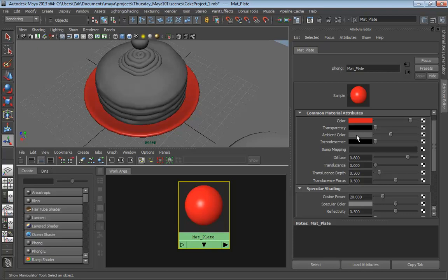They're much lighter shaded. This will tend to make objects look like they're emitting a little bit of light, like they have a little bit of glow. You can use this to your advantage for things like characters' eyes if you want them to look just a little bit more vivid, or plant life, or skin shaders. You can give them just a little bit more life, and in a way, it kind of starts to simulate subsurface scattering.